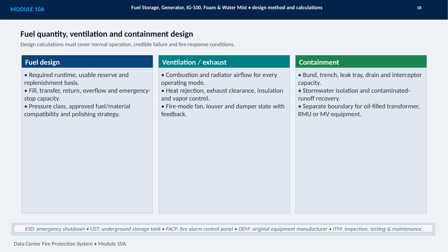For fuel design, we establish the required runtime, usable reserve, and replenishment basis. We also verify the capacity of fill, transfer, return, overflow, and emergency stop systems, while confirming pressure class, material compatibility, and the need for fuel polishing.